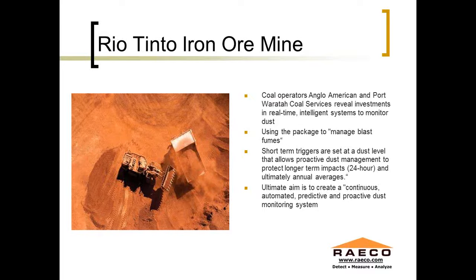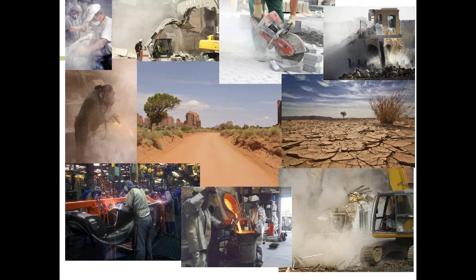So a lot of times, when we think of photometers, we think they're really good screening devices. We always say that a photometer is very precise. We're going to provide very strong, repeatable data, but we're not always going to be 100% accurate. And to get the most accurate, you're going to want to do gravimetric sampling.